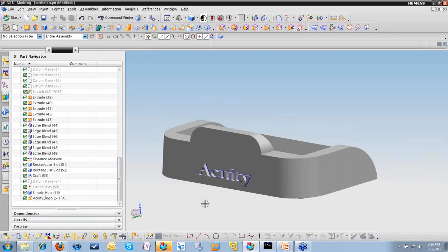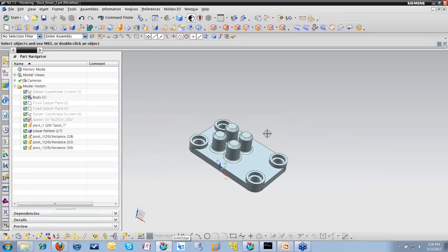Again, you can get really complicated with this stuff. You can push the limits, and as you saw in that other NX75 example that I was demonstrating, you can pick multiple features, and that's a huge benefit. Because just one extrusion is not going to really save you a bunch of time a lot of times. When you're grouping a bunch of these things together and saving yourself some time, that's where the power is. So with that said, that's pretty much all I wanted to present today.